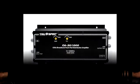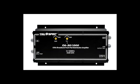So sometimes this control is labeled as a slope or a tilt. Okay, and of course over here you have a minus 20 dB test signal. So if the signal is really strong, you connect your television set straight into this output here, and this extremely strong signal is brought to a manageable signal strength that the TV can handle. And on the output as well, there is a 20 dB test output. Okay, but the main connections are: here's the input, here's the output, here's the gain, and here's the slope.